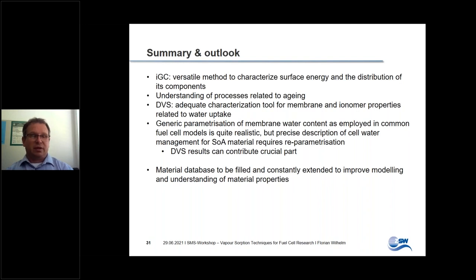Of course, you need further data. You need the membrane equivalent weight. You need, for example, the membrane proton conductivity resistance as a function of the humidity. This needs to be measured with different instruments and different setups.